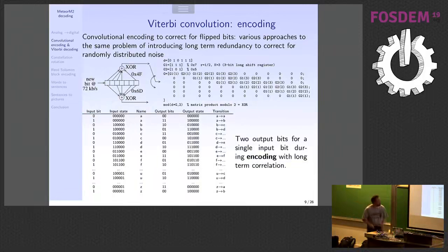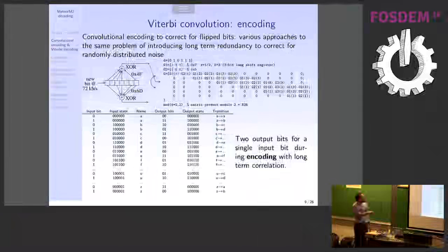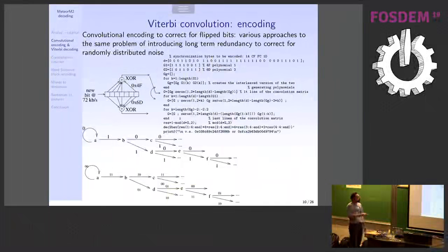So once you've discovered the state machine expression, you can write this as the evolution between the various states. So previously I had given names, A, B, C, D, to my various states. And then you can draw the state machine. So A stays in A, and goes to B if you have a 1. These are the input bits. So if A is fed a 0, it stays at A. A, when it is fed a 0, will output 0, 0.